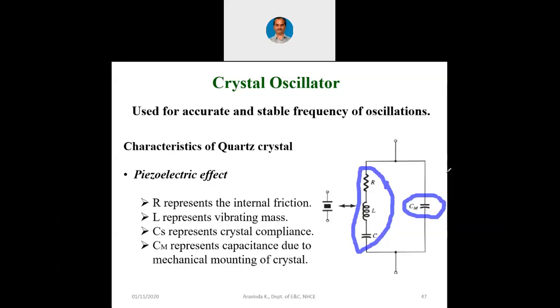If we connect the crystal in series with the feedback circuit in that way, now we can predominantly choose the series resonant frequency only. If at all you connect the crystal in parallel at the output of the amplifier, of course, again by making a feedback connection appropriately, we can make use of the parallel resonant frequency of the crystal. We will see that in our examples in the next slides. So as we can represent the crystal in the form of an equivalent circuit, let me show you the oscillator circuit itself, which we are going to use now.